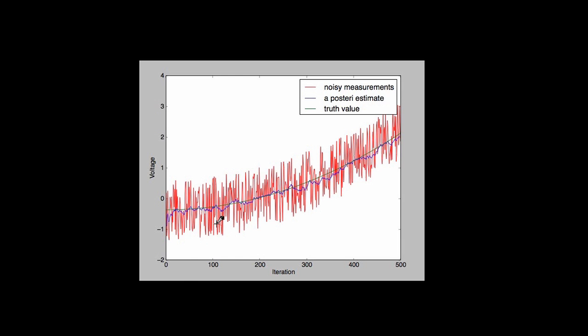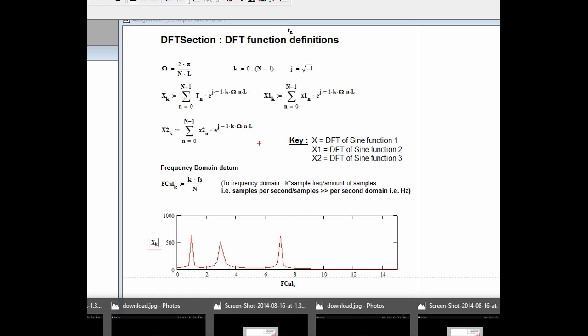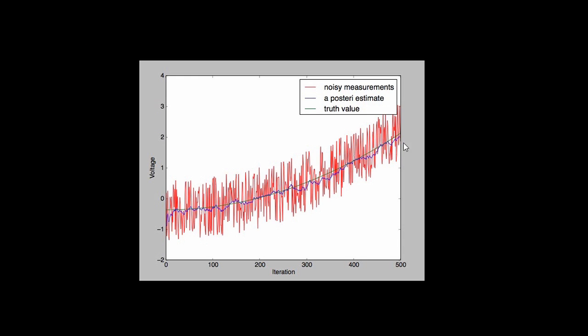So you would expect something like this, where you have a peak at your low frequency and a peak at whatever noisy frequencies there are. So you'll see where your noisy frequencies are to design your filter and make the best Bode plot for your filter. Just remember your filter must keep up with the quickest change. Remember the Nyquist rate: the sampling must be at least double that.